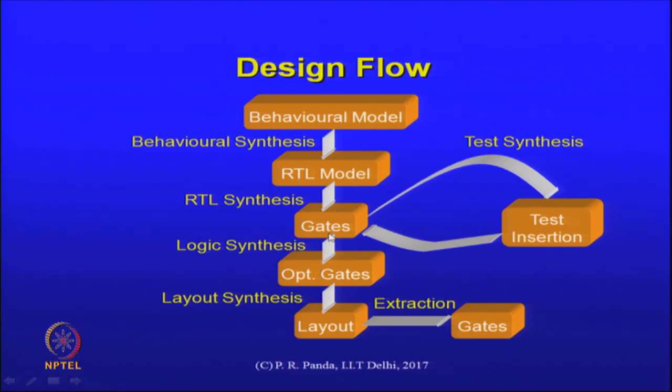What is indicated here is not necessarily optimized, it is one form of representation of our design. A set of logic synthesis steps would take us into a more optimized form of design of that same gate level netlist. Then we would go through a physical or a layout synthesis to generate the layout for us. That would then be what is input to the next stage of fabrication and so on.